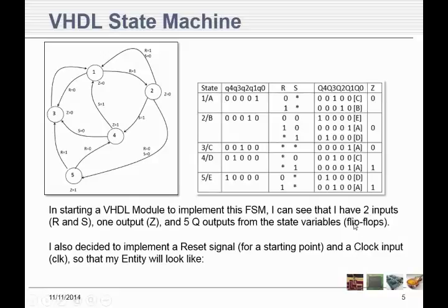You could name it ZZ or something like that, something that you know Xilinx won't pick up as a clock, because it's been my experience that if you had a combinational circuit and you didn't need a clock, Xilinx would put one in the test bench.